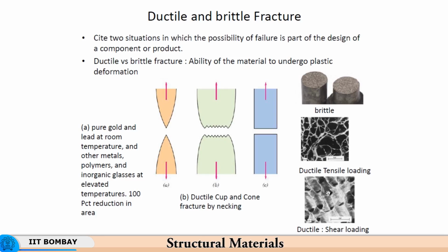That is because as you go on deforming, I told you that an absolutely clean material is a hypothetical concept. So, you have some inclusions, you have particles, intermetallics of different hardness, and now as you go on deforming the material, there is nucleation of voids in the material, and these voids become bigger and bigger with increasing strain, because now the voids have ligaments which are present in between the two voids. In fact, the shape and size of the void gets defined by the ligament. Initially, the ligaments would be very thick, so voids would be in the form of very micro sized voids.